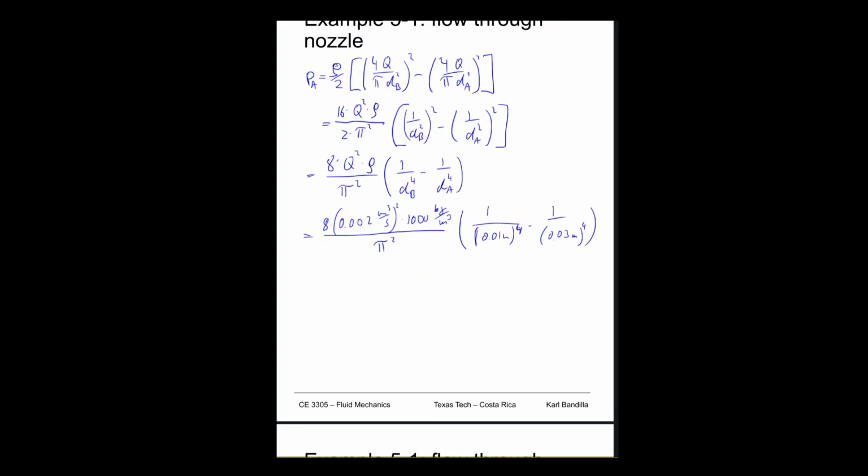All right, and we can plug all that in. And then I get 320,225 pascals. So make sure that that actually works. We're dividing by meter to the 4th. We have 6, we have 3, so we have 1 meter left on top. And we need a kilogram meter per second, so yeah, we get newtons per square meter. So that then gives us 320 kilopascal.